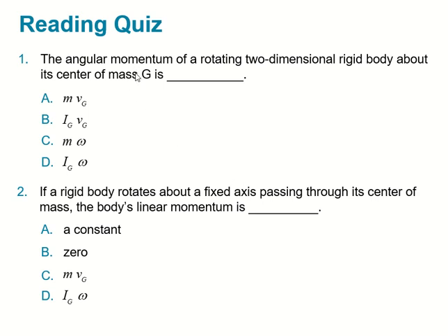So you know that regular momentum is your mass and the velocity. The same thing, angular momentum is also mass and the velocity. But when you deal with the rotating stuff, then the mass is now called the mass moment of inertia, which is this guy. Because like I said, everything that wants to stay, tries to stay, even in rotation, even if we push it to go in a rotation. So right before that, you have the mass that's called the mass moment of inertia, times, of course, your angular velocity.